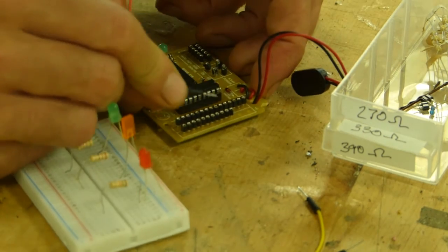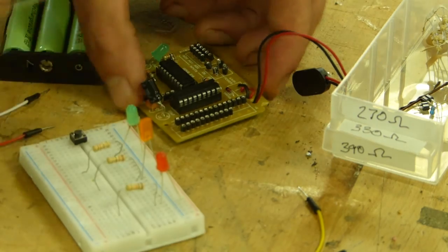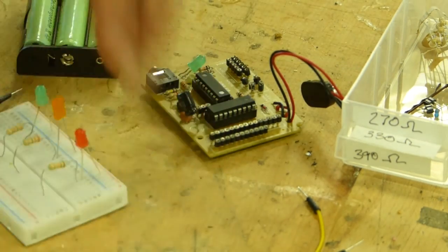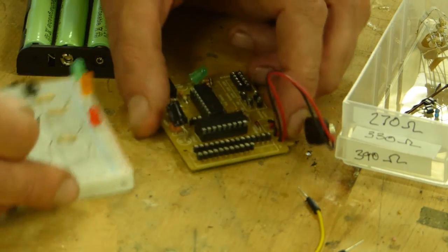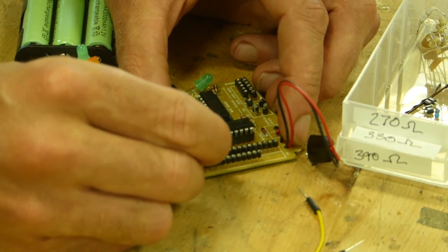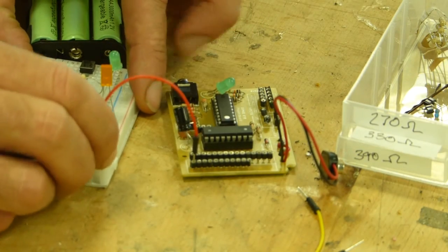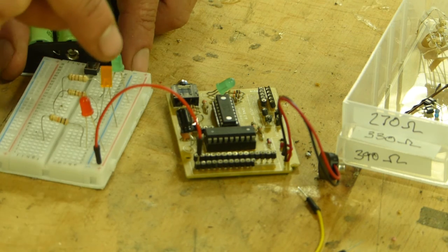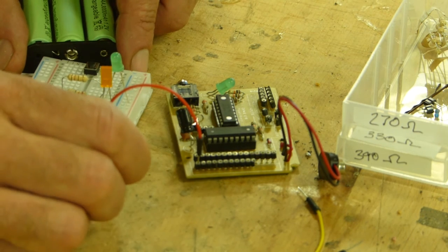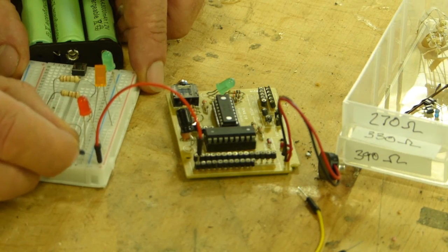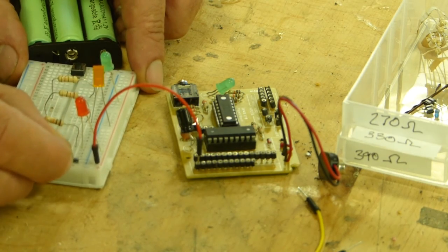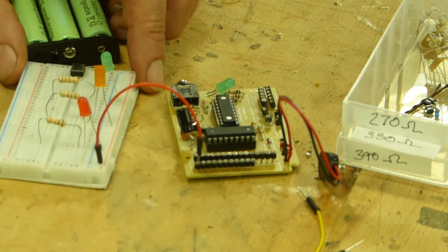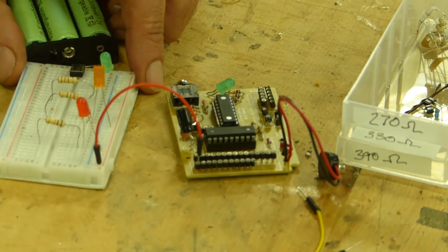So if you remember all of these lines here, when we made this board, remember on the back all of these plus volt lines are connected together, which means they're common, they're all shared together. So we can actually just transpose that. If I just plug the first one onto this rail here on the breadboard, if you notice we've got a plus line all the way along that line, that means they're all connected electrically. Similarly, this blue minus volt line, 0 volts, is all connected together as well. Now we're not actually going to use the minus volts, we're only going to use the plus volts. So it means anything on that line is connected.